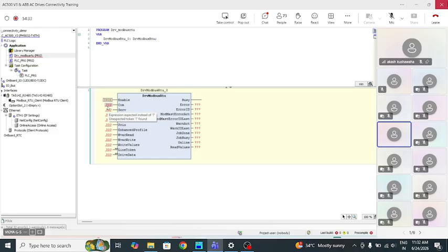In case of standard PLC, the inbuilt COM port will have COM 1. Then if you're using an extension board like CM5610RS, in that there are again two COMs. So you can number it as 2, 3, and as you increase you can give the COM number. So here I have added in slot 1, so I will give COM 1.